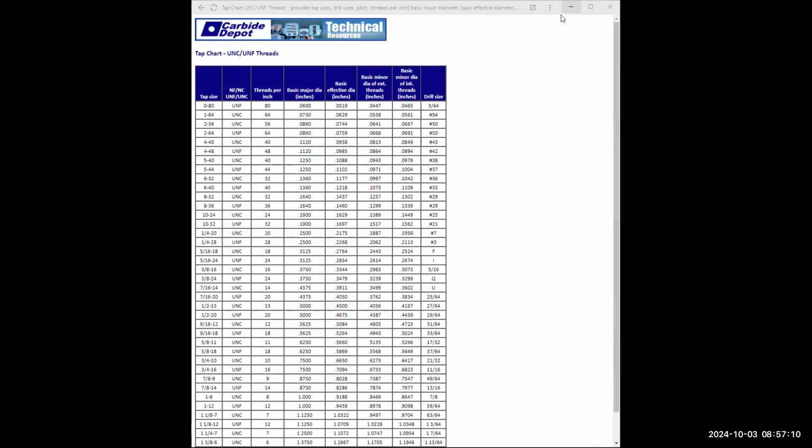I selected the lines I want to change. I'm going to enter. I'm going to type in P for property, enter. I'm going to type in LT for line type, enter, and I'm going to type in hidden, enter, enter. Now it's a hidden line, as it should be.